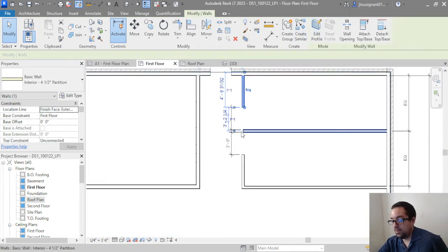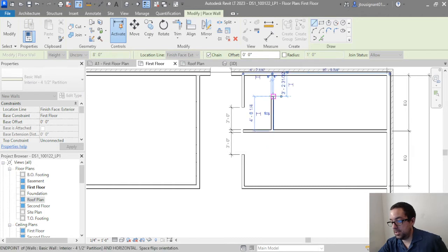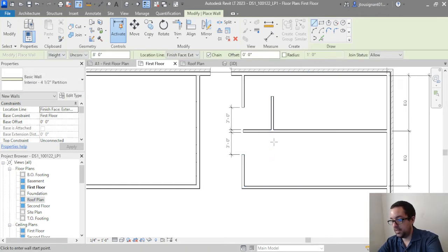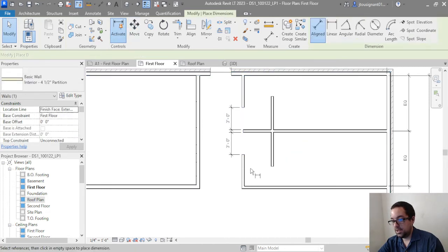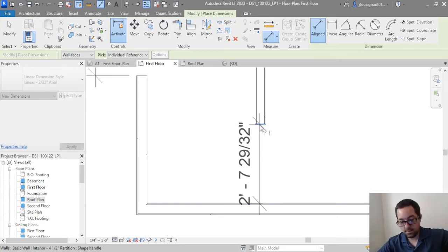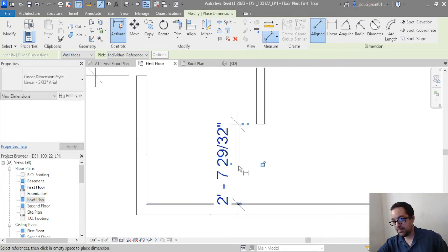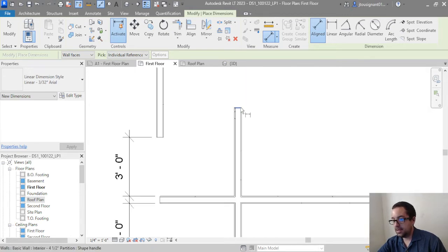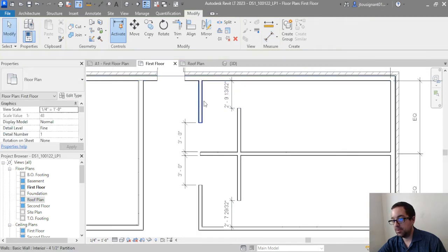But now if I don't want to have people see directly in, I need to have another wall. Again, it takes up a little bit of square foot, but hands-free contact is nice. And do the same dimensioning. Remember, your last click for your dimensioning always needs to be in a blank space, otherwise it won't remember what you did.